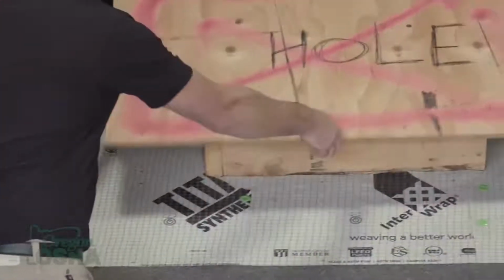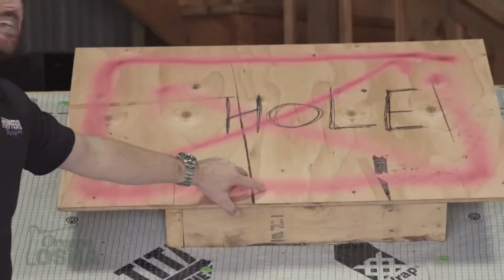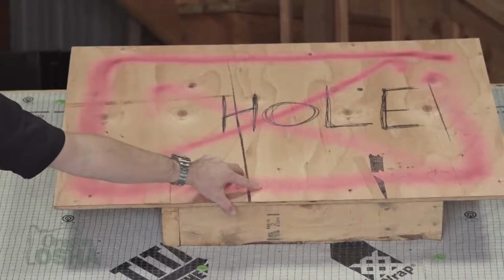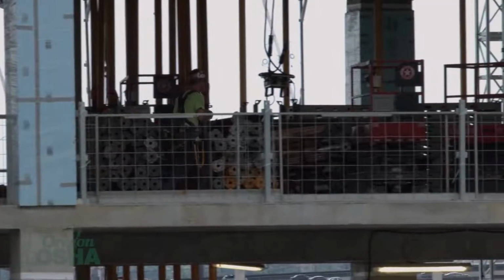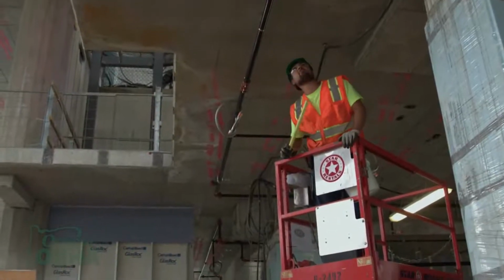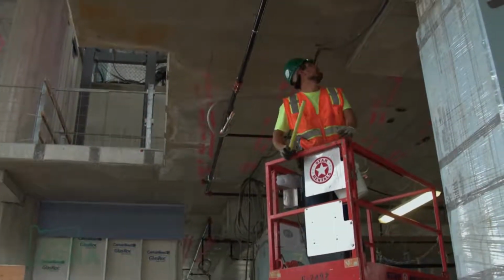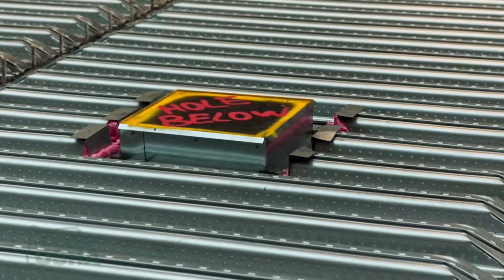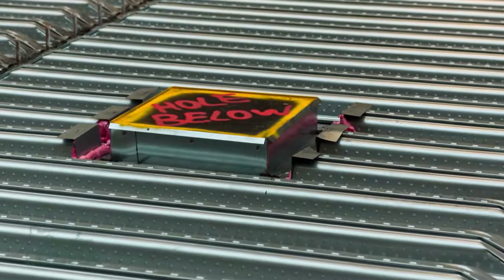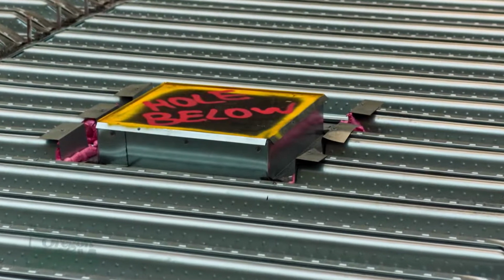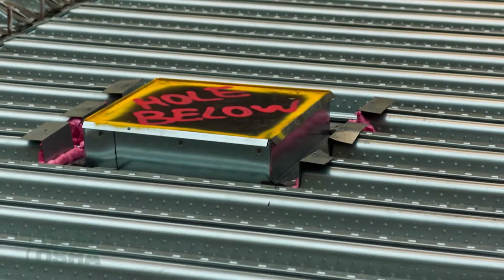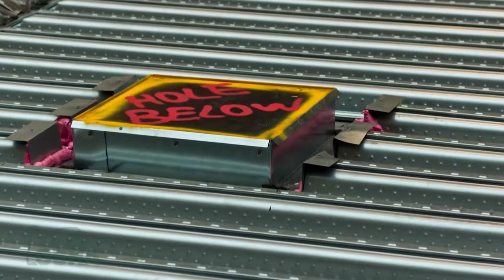Hole covers are used to prevent falls by covering holes in floors, roofs, and other walking working surfaces. They need to be able to withstand, without failure, twice the weight of the employees, equipment, and material that might cross over. They also need to be color-coded or marked with the word hole or cover, and be secured when installed so that accidental displacement is not possible.